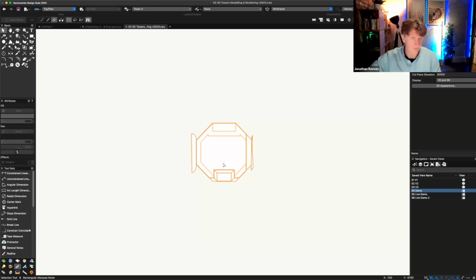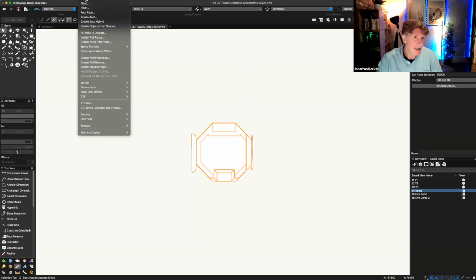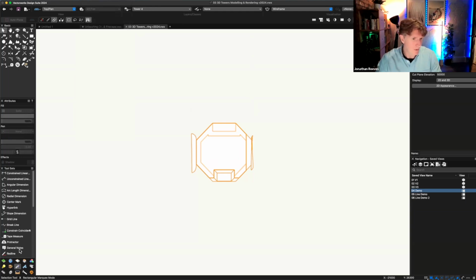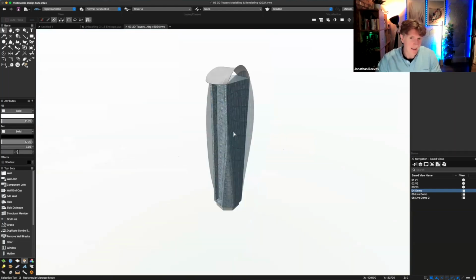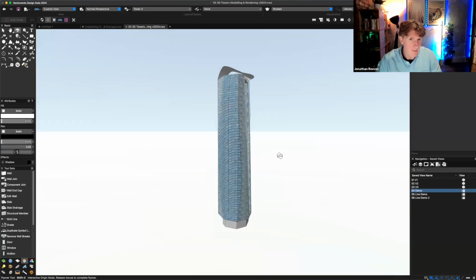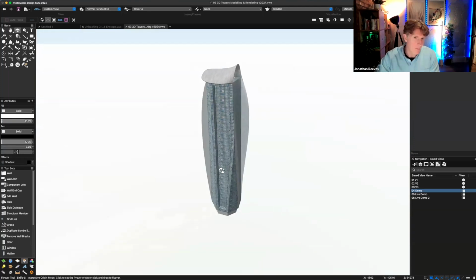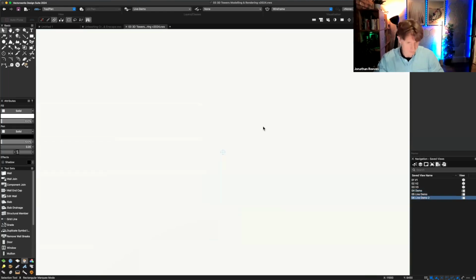You can see it update its geometry depending on the height that you're telling it to slice through. The auto hybrid's a really useful thing in BIM because if there's something that you can't model with the BIM tools, regular walls, windows and doors, you do this sort of freeform modeling, and then you say, give me an auto hybrid of what this thing would look like above or below at 30 meters. So it means that you can represent things two-dimensionally from very complex objects. It's a really important tool in the armory of BIM. Let's go on to my live demo though and see how this works.